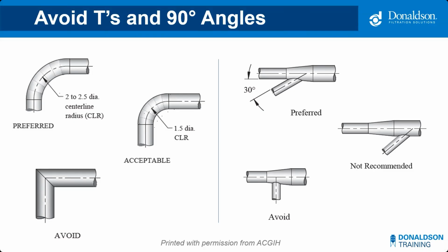A 2 to 1, a bigger sweeping elbow, has 0.19, and a 2.5 to 1 has 0.17. The lower that value of velocity pressure loss, the less static pressure you need in your system. And now the 90-degree branch entries: a 30-degree is 0.18 inches of loss, a 45 is 0.28, and of course a 90 in the elbow is a 1 velocity pressure loss. This was added up to determine the total static pressure required in the system when selecting your fan.